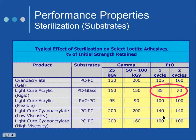If you look at glass and polycarbonate, they're completely different animals, right? So I think that's probably what happened, and had we been bonding PVC and polycarbonate, it might have been much higher. So you really need to watch that. You obviously have to do your due diligence. We don't sterilize our materials before we send them for biocompatibility, but you certainly have to do a sterilization study on anything that you make.